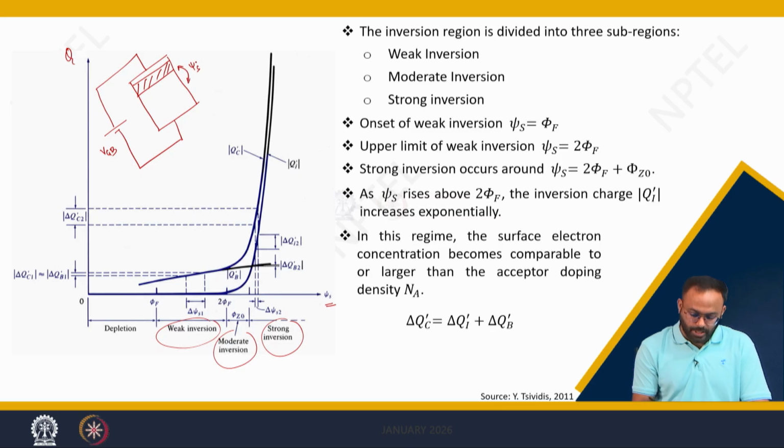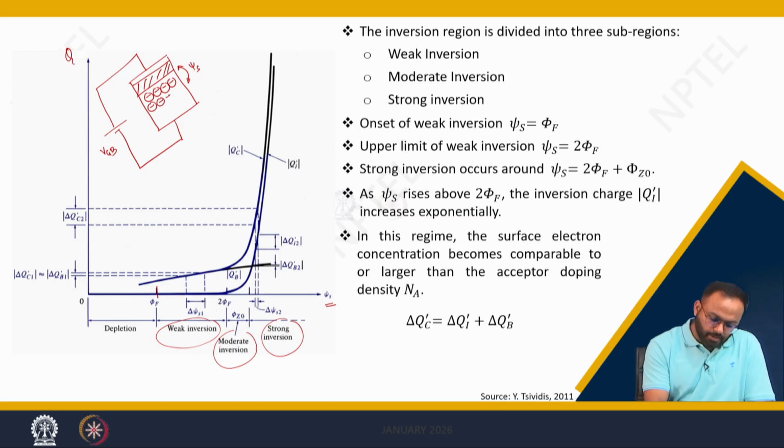The surface potential reaches the value of phi_f, which gives you the depletion, but beyond the depletion there is some amount of mobile charge present. For simplification we considered the concentration of these charges negligible, but they will give some amount of conduction when this two terminal MOS becomes a part of a MOSFET.